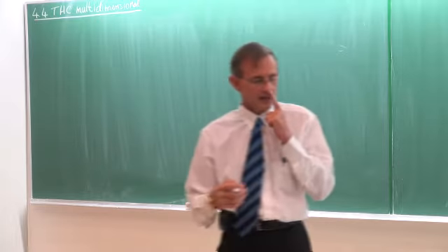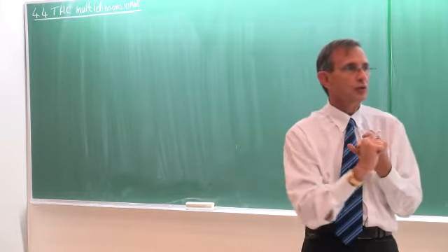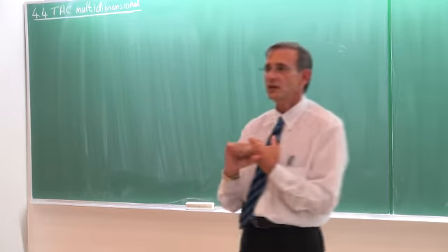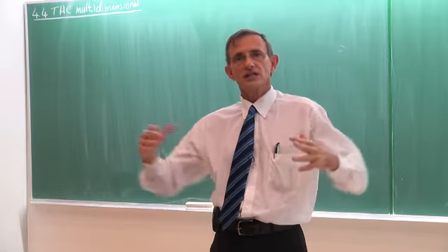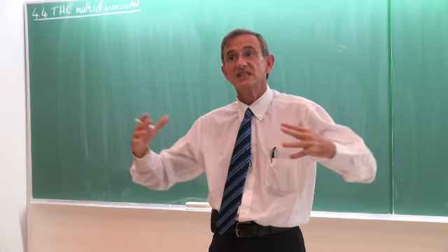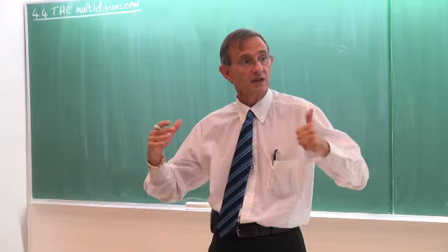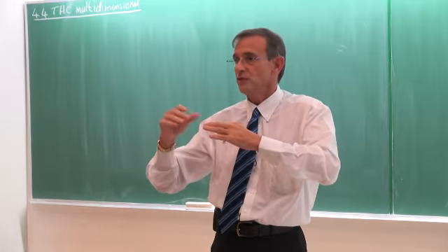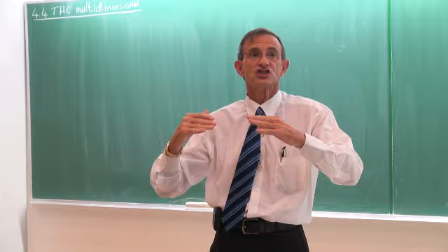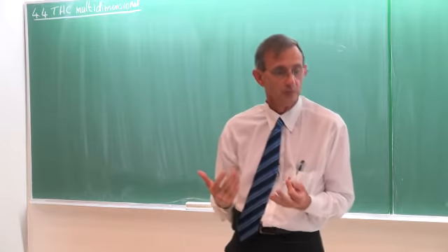Okay? Then the third part of the work was we've looked at semi-infinite solids. Semi-infinite solid is a big body, and the temperature doesn't change inside it. It's a very important assumption. And then, very close to the surface, we can see how the temperatures change as a function of time.